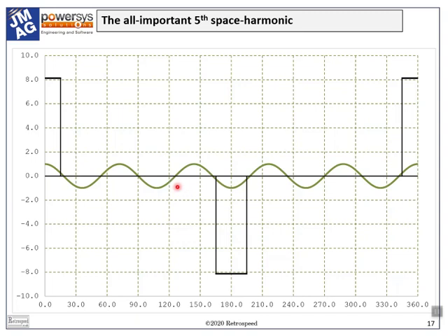The peak value of that rotating component, by the way, will be 3/2 times the peak value of any one phase. The amplitudes in the diagram have been scaled so that the fifth harmonic amplitude is 1.